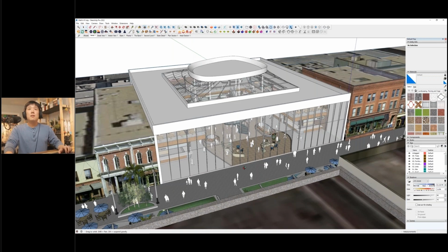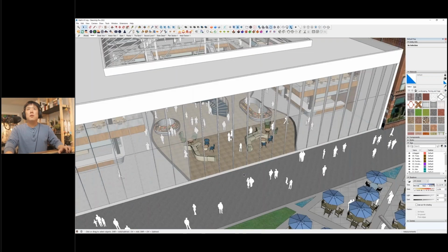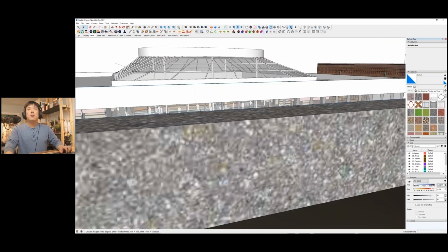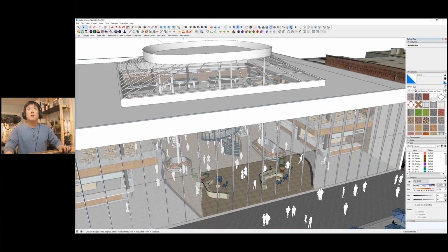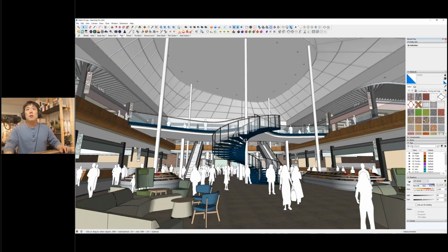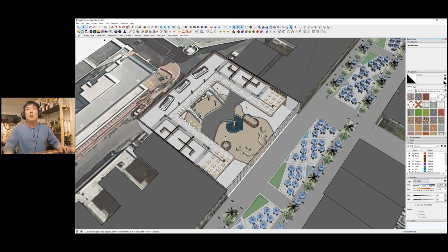So this is again a commercial setup where I was showing a couple of the rendering images. And as a quick tip here, I usually set a couple of scenes up on top so that I have a first one as a modeling view. I always come back to this view if I need to model something. But when I go into presentation, I set up a series of scenes so that I can quickly flip through them to show people what areas of interest there are.